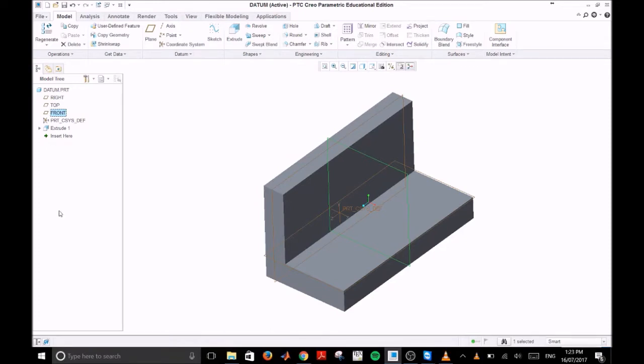However, some issues can arise if we want to locate a part off-center. For example, if we wanted to add a web to this feature. We can get around these limitations by creating a new datum plane. To do this, in our Datum tab, we select Plane.